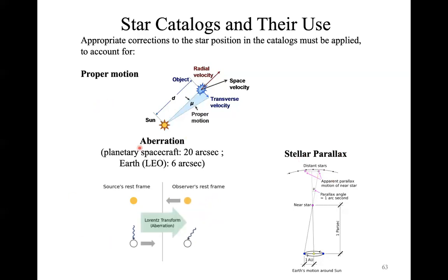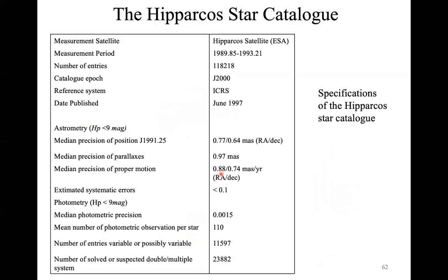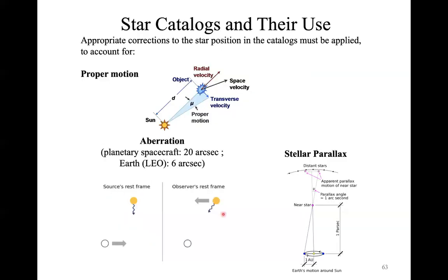The third source of error, given by, for example, the knowledge of the orientation of the stars in the inertial reference frame, is the aberration. However, this one is not related to the star catalog, as you can see. The other errors are not really important for us. But the aberration is not related to the star catalog, but is related to the motion of the spacecraft.